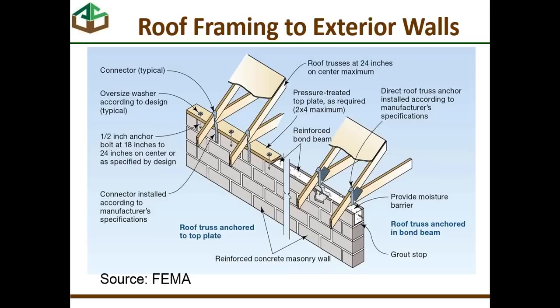The other way, and one that I think is more typical because it's sometimes easier to make adjustments in the framing, is to put a sill plate, if you will, or a pressure-treated top plate on top of that wall, anchor it into the bond beam, and then take a strap from there. Now you notice that in the left-hand figure, this probably illustrates more of what you might have to do in a retrofit situation, because you have a strap attached to the masonry wall as opposed to anchored in the masonry as you see here. But either way, the important part is the connection.